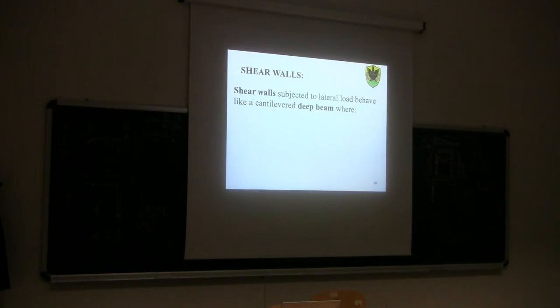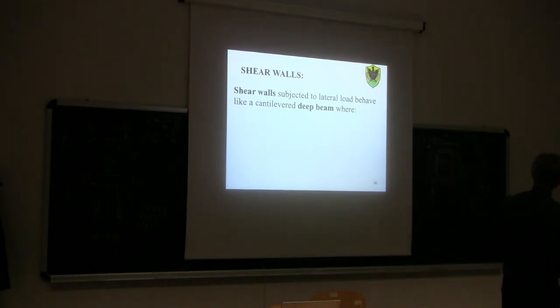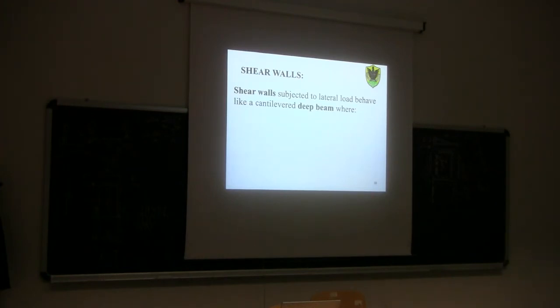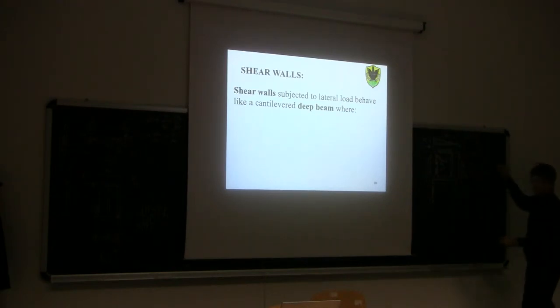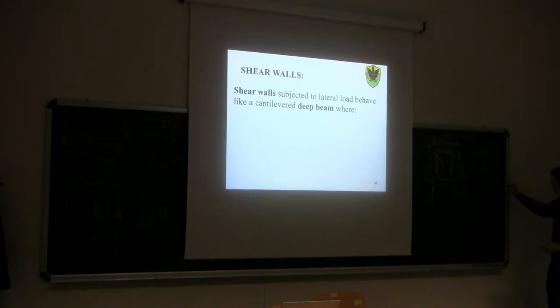So let's say that the nails are spaced S. We calculated the unit shear, V. So V is the unit shear, the shear by unit length. If I know the unit shear, in order to find the total shear in one nail, I will have to multiply the unit shear, which is kilonewton per meter, times the spacing of a nail, which is meter. And then I get kilonewton, shear force.